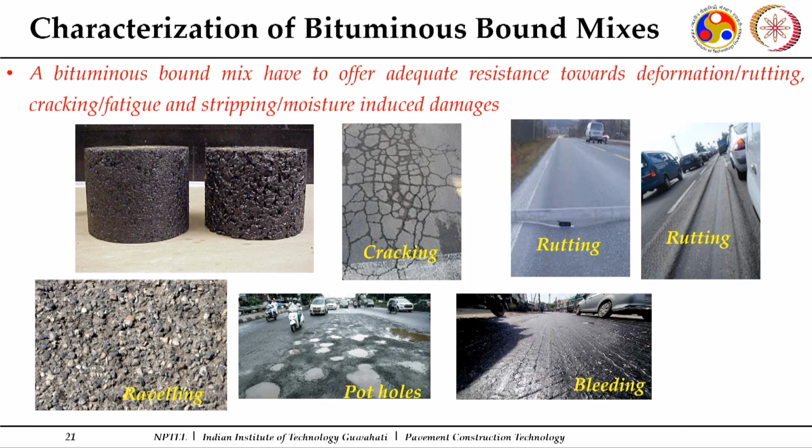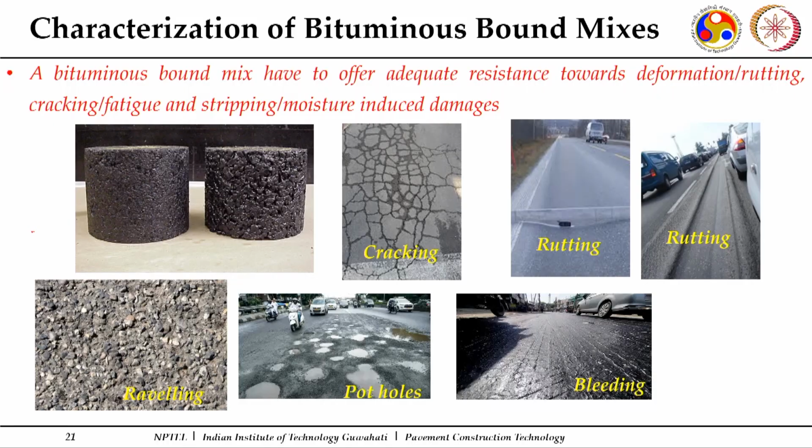Now under these bituminous bound courses, we discussed some requirements for the binder to be used and the aggregate to be used. Once you prepare a mix, with different sizes of aggregates bonded together with the bitumen, finally this is the mix which is going to be laid in the field. So this mix needs to be ensured for different characteristics, and for laboratory evaluation we prepare cylindrical specimens through these combinations of bitumen and aggregates.